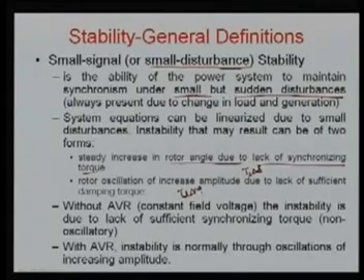In this case, it is oscillating, and you can see it keeps on increasing with oscillation and the system becomes unstable. Here, the angle keeps on drifting, with a continuous change in delta, which is aperiodic, and that is due to the lack of synchronizing torque.